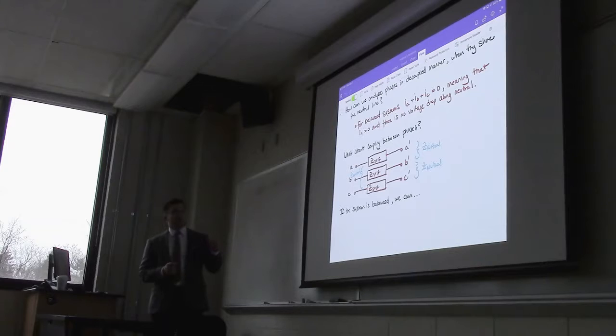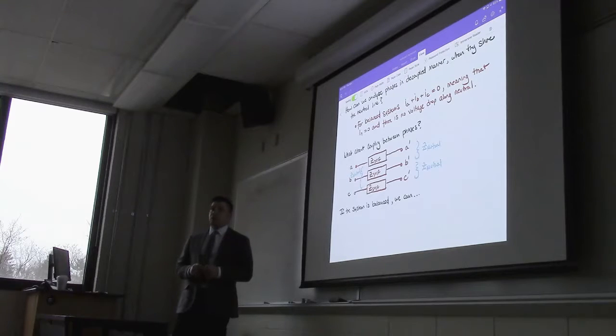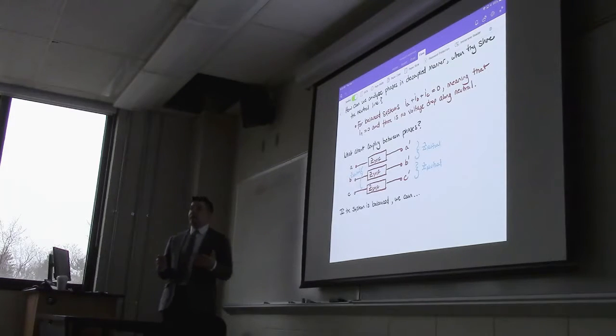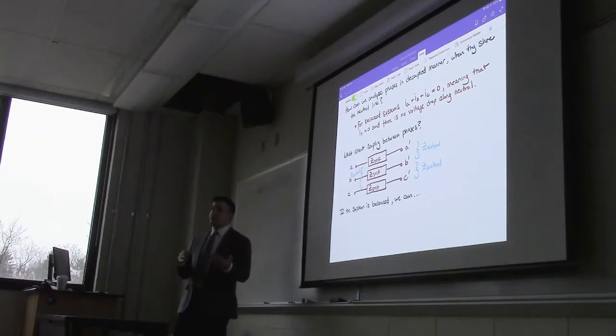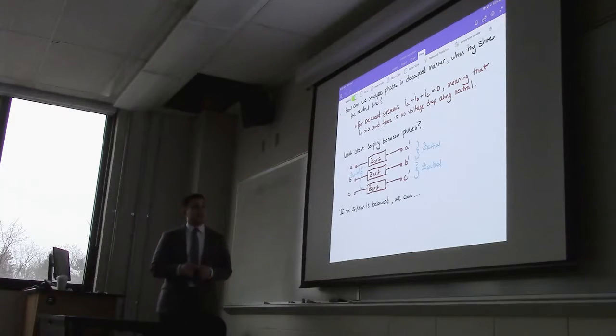So what is the coupling between phases? It's the mutual impedance between those lines, which in most cases is going to be represented by an inductive element, which represents the magnetic field generated by the individual lines running along the transmission grid. There's also coupling between the phases in synchronous machines, because those also have a magnetic component, but again, we'll find a way to represent that as an equivalent within the machine model. So we don't have to ignore the mutual inductances, but we do have to find a way to represent them accordingly.